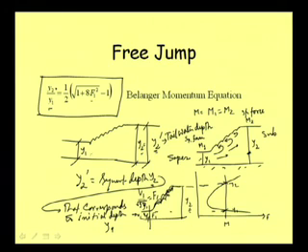We cannot go by this relation directly. Say for computing the hydraulic jump, or for deriving the relationship between Y1 and Y2, if this is not a rectangular channel, then we need to go for a trial and error procedure.